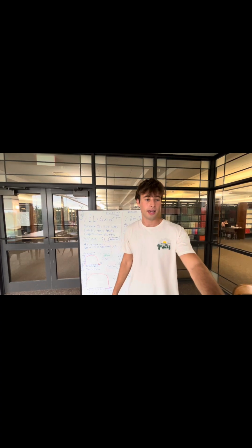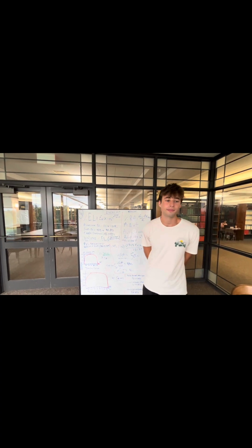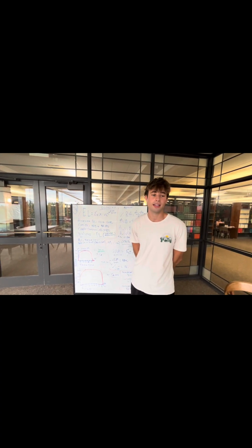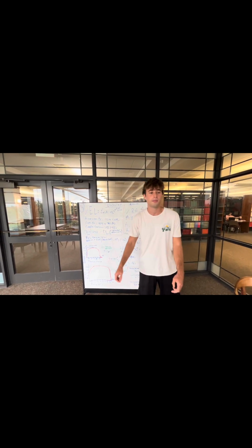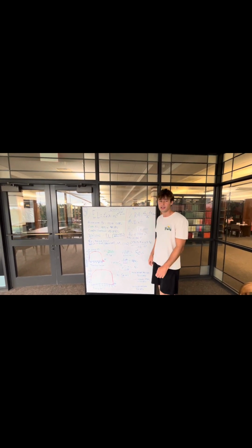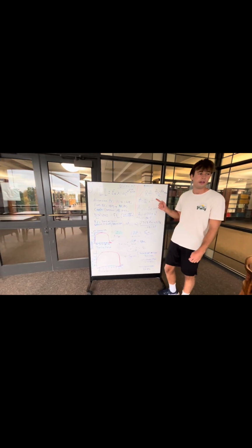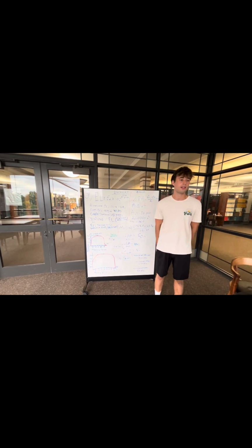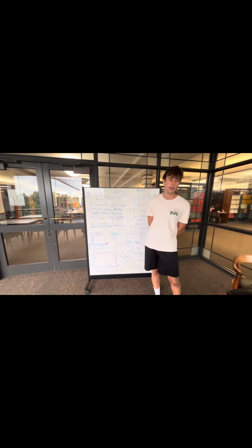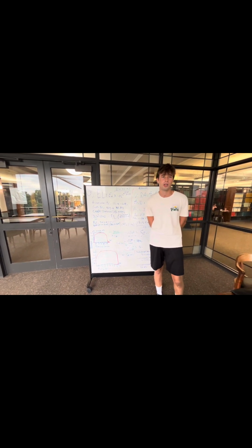To summarize, the tensile strength is the maximum stress at the peak of the curve, and ductility is measured using either percent elongation or the percent reduction in area at fracture. Together, these properties can tell us whether the material is strong, brittle, or capable of absorbing a lot of deformation before failure.